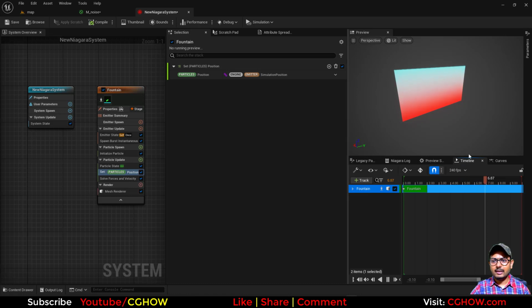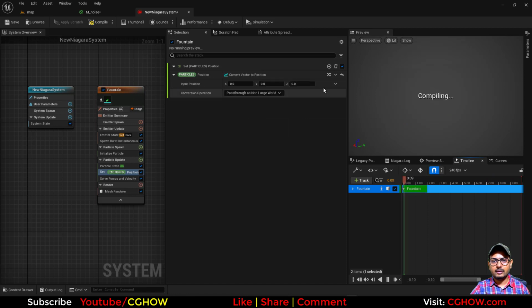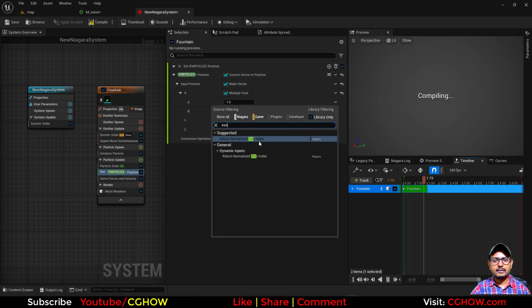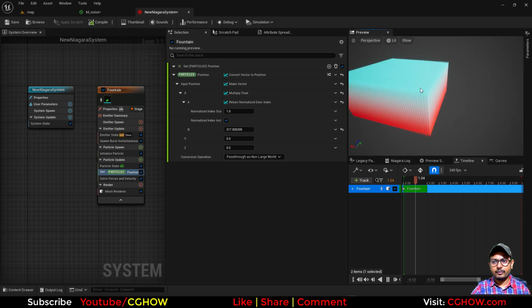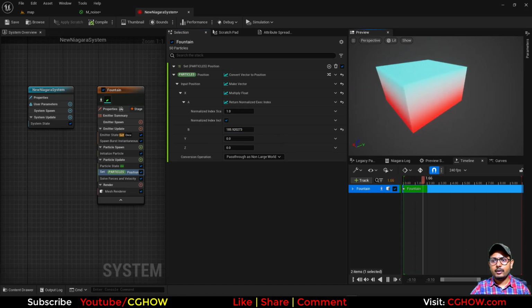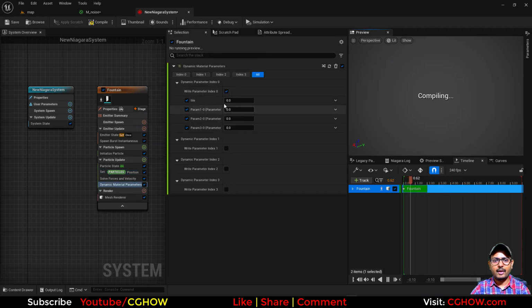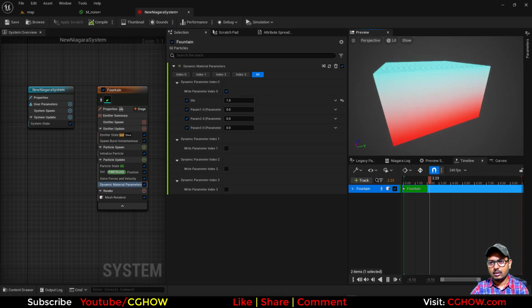And now this axis, I want the x-axis, so I'll make a vector of this, then break this, then multiply the x with execution index, and if I increase this value, it will make an offset, and you choose how much offset you need. Okay, then in the dynamic parameter, you have this tile 0, let's make it 1, or 5, or let's make it 1.